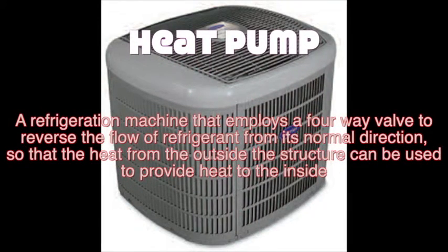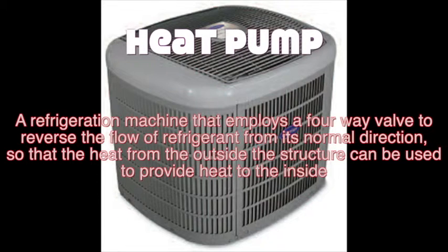Now we're at the heat pump. It's the heat pump: a refrigeration machine that employs a four-way valve to reverse the flow of refrigerant from the normal direction so that heat from outside the structure can be used to provide heat to the inside. That's a heat pump.